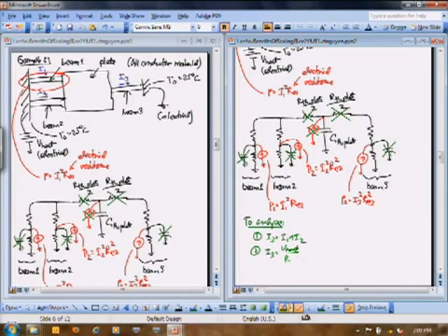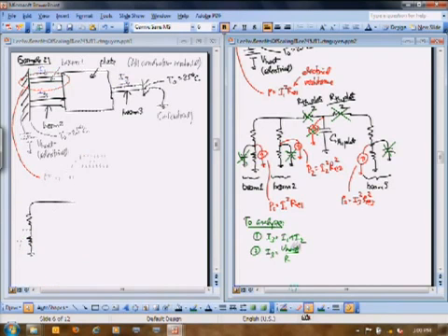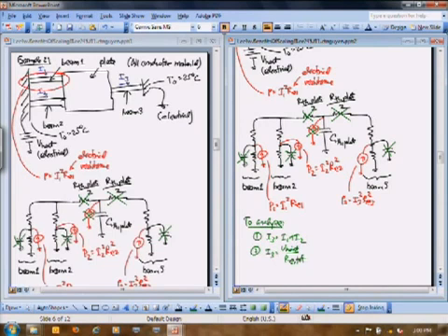So you solve the electrical problem first, determine all the different resistors, get all the powers, then get all of the thermal values, create your thermal circuit, input those powers in the thermal circuit, and then do circuit analysis again to determine the temperature at each of the different locations, to get the time constant and all of that. Okay?